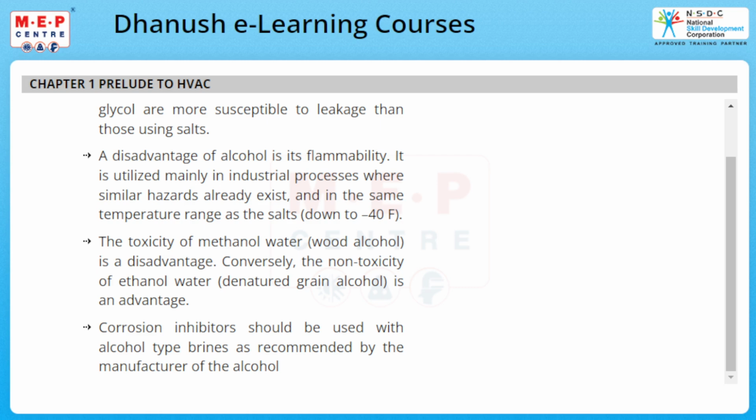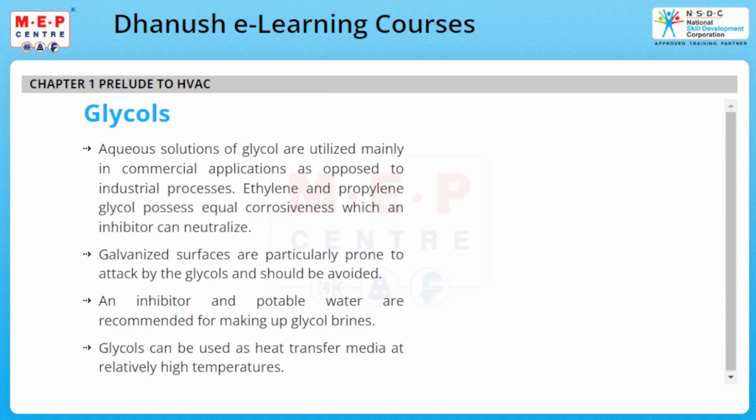Let's understand glycols. Aqueous solutions of glycol are utilized mainly in commercial applications as opposed to industrial processes. Ethylene and propylene glycol possess equal corrosiveness, which an inhibitor can neutralize.